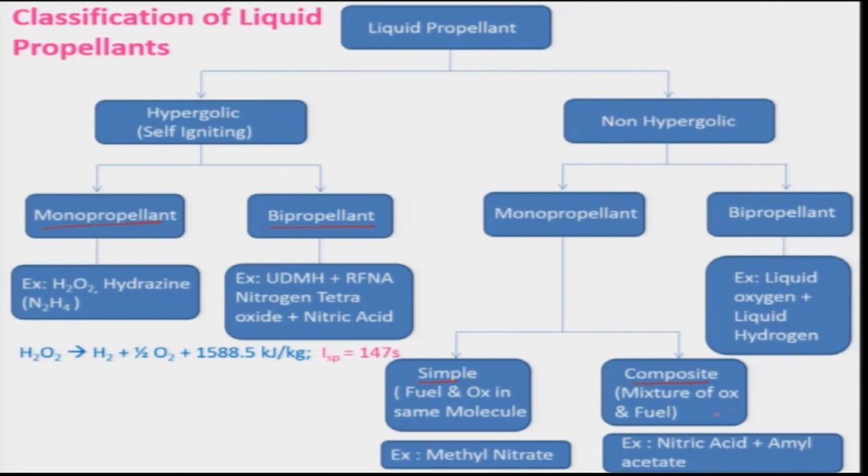It can be used as a monopropellant, but for this one has to provide a certain amount of ignition energy to initiate the combustion. And the non-hypergolic bipropellant is used very much, because it is quite safe and also easy to control a lot of things.